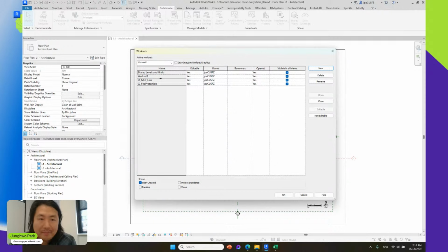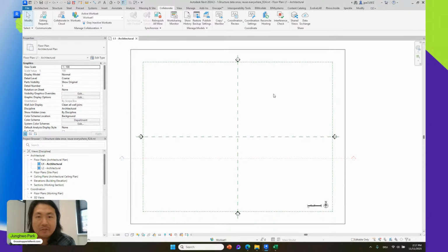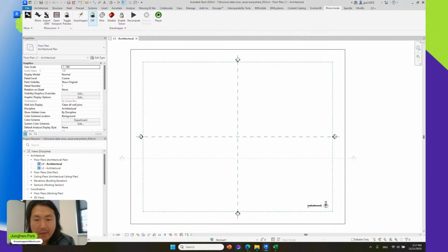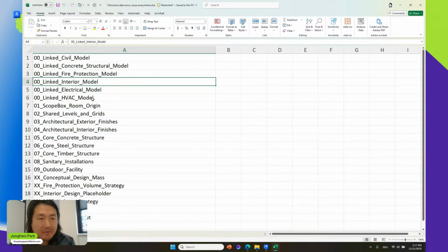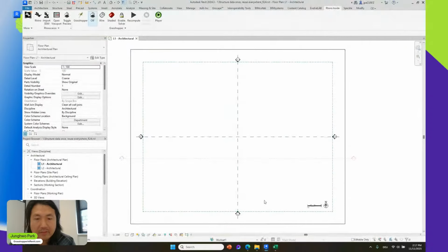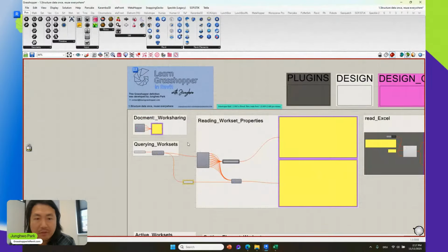And you have to share this workset-enabled file as a template to different teams or even different companies. So what I want to automate by using Rhino.Inside Revit is this: we can actually have a common workset template, say a table from Excel, which is quite common to stream the Excel file in Grasshopper. So I'm just opening our Grasshopper file here, which you can also download later.